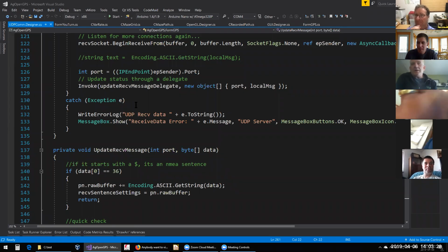Okay, so was there anything else? Just a question about the relay board. You used single pole relays. Would it be possible to use dual pole? Because some people have motor-driven valves on the sprayer, and so they need to put in plus and minus, and then close minus and plus.